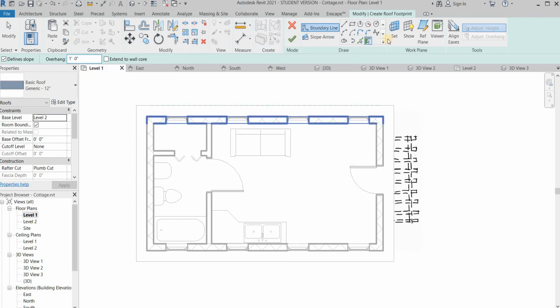And when I move my mouse cursor over it, you begin to see the dotted outline, right? You need to make sure that the correct wall is selected, and also the correct side. Your mouse needs to be moving towards the outer edge of the wall. So I'm going to click here, and you begin to see some numbers.